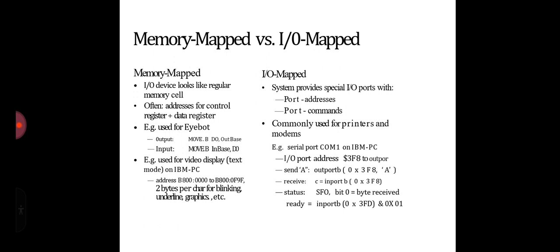And the last is the direct memory access, which allows input output devices to access memory directly without involving the CPU. DMA device acquires bus control and reads or writes data while CPU is doing arithmetic. Parallel processing equals higher speed. If both CPU and DMA device want bus access, one has to wait a few cycles. Useful for block storage devices, for example disk drives. For data transfer, we have to wait for the right sector to come around. With DMA, CPU does not have to wait.